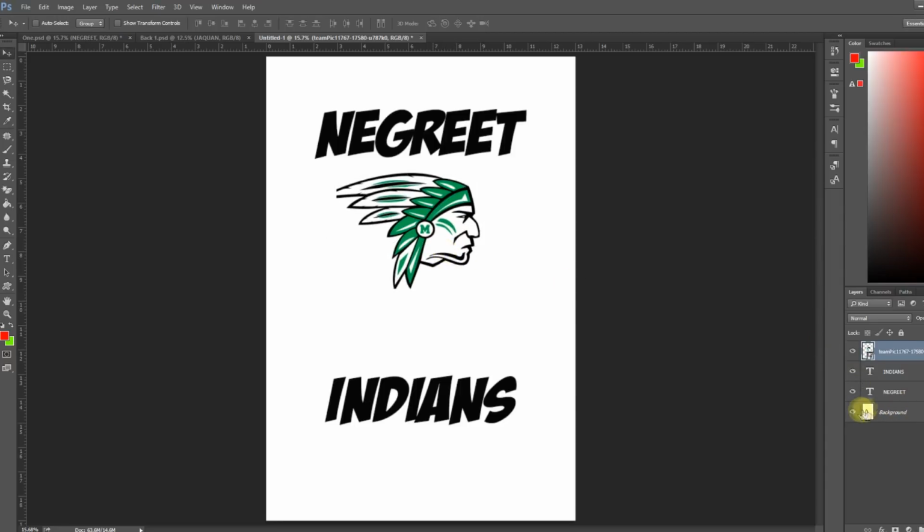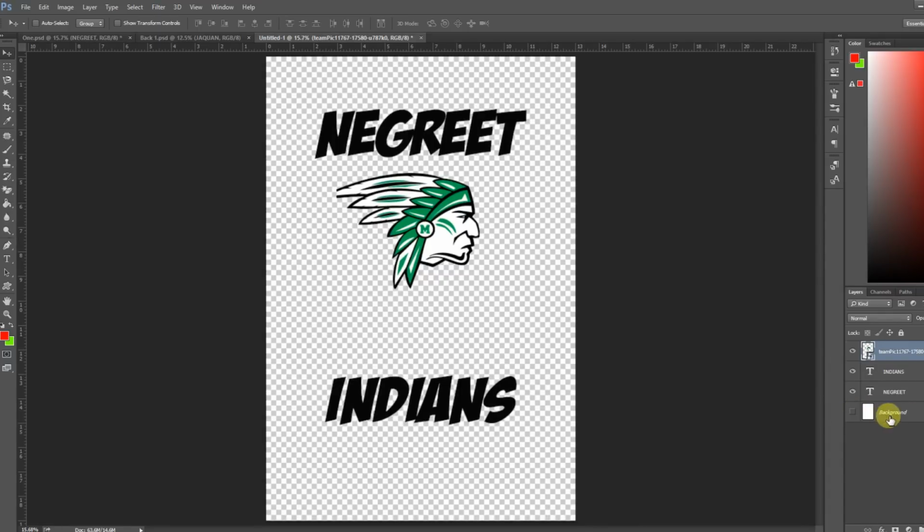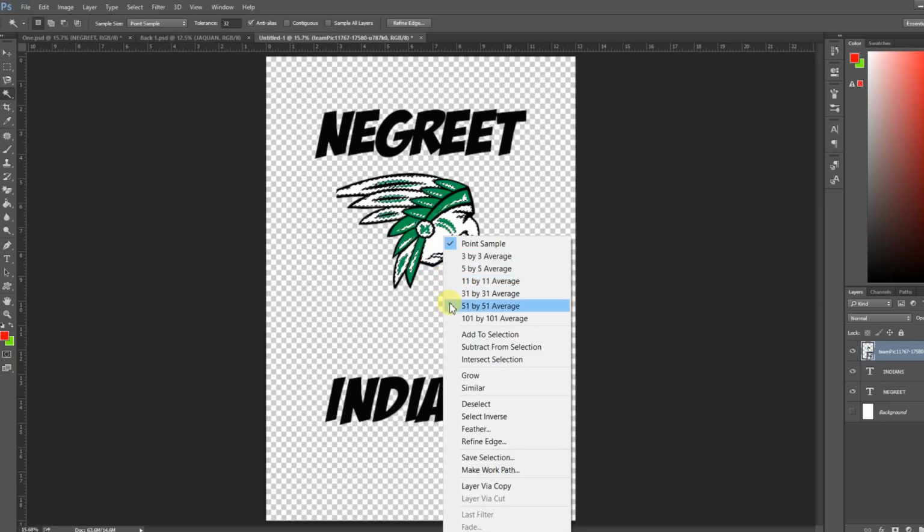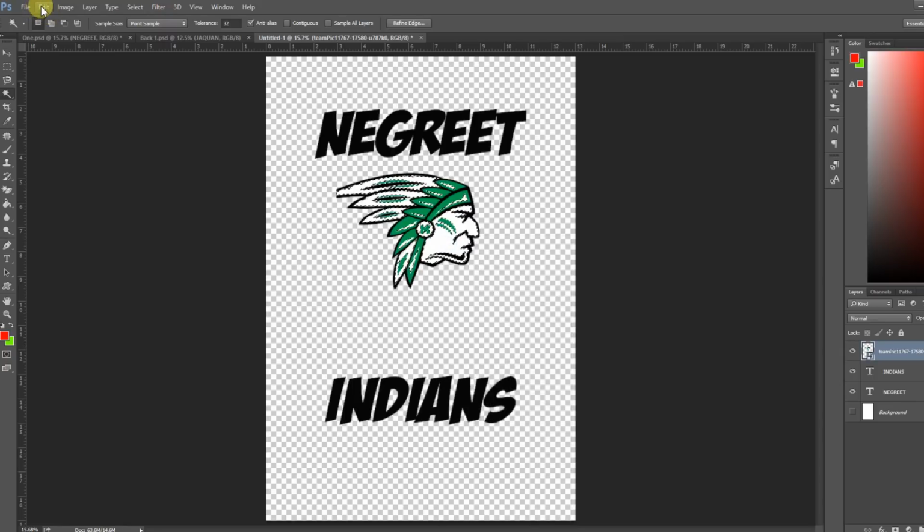Okay, so right there I'm going to hit enter, and I'm going to erase this background right here so that I can see things a little bit better. So now what I'm going to do is remove all of the white from here. And to do that, I'm going to use the magic wand tool, and I just click on the white. And actually, before I do that, I've got to take another step. So I'm going to hit edit and undo, and then I'm going to just pretend I want to use the eraser tool just to flatten it. That's pretty easy to do.